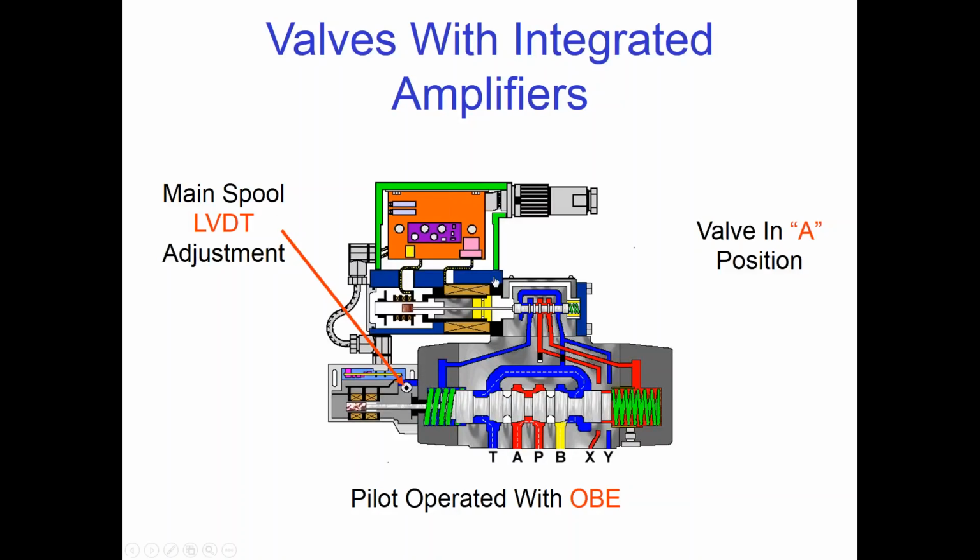So I'll leave that up to what everybody else thinks. Personally, what I've found is that a valve that is on the machine, subject to all of the dirt and the heat and the vibration, is just, to me, not the best place to put a sensitive PC card. I know a lot of people disagree with me. It's good to have everything all in one place, so that when you're troubleshooting, you eliminate troubleshooting time, because you know something's bad, well, just change the whole thing. Well, there's a lot to be said for that. But to me, that's just not the best place.